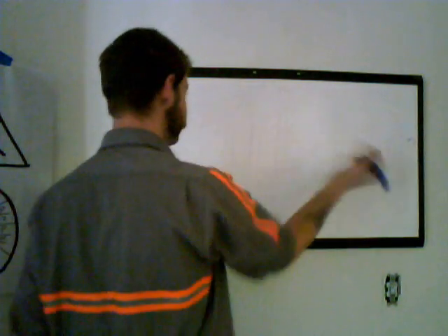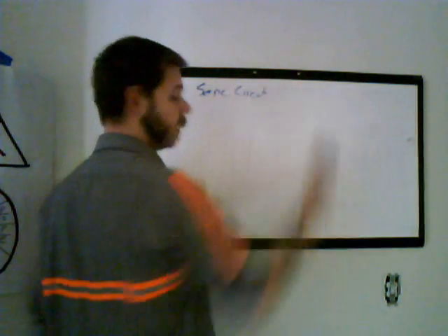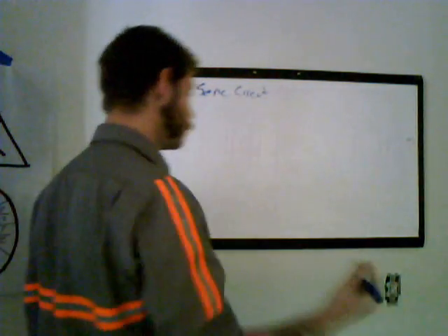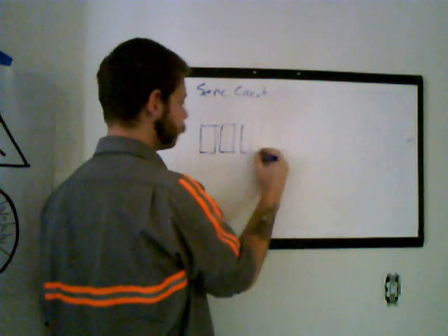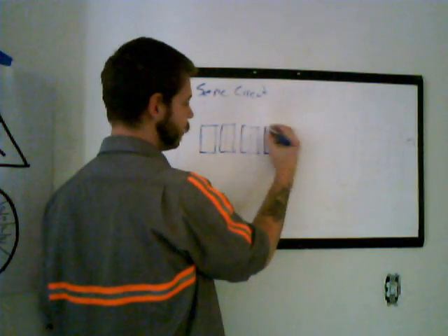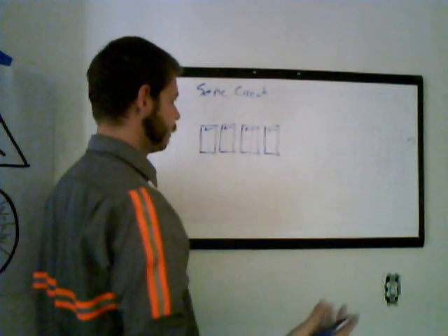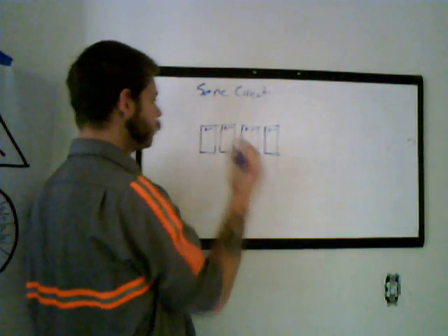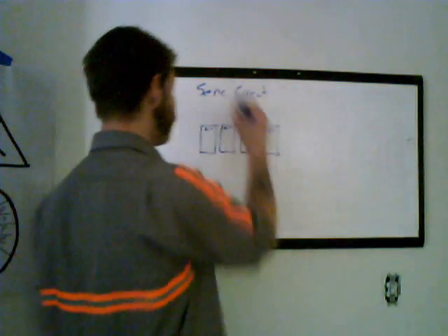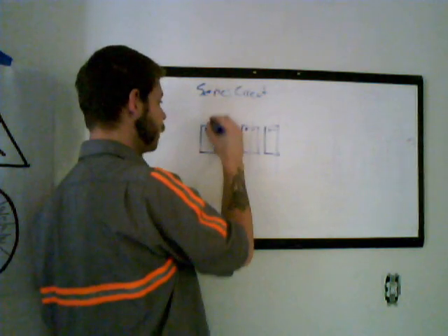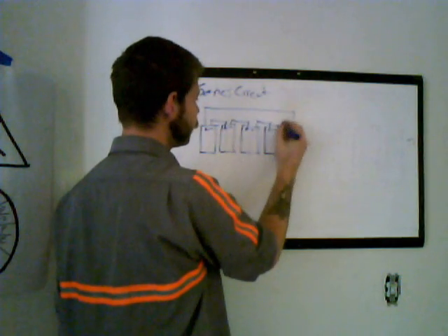Okay, so series. We just finished going over basically series loads. Let's put some PV panels together. PV panels are sometimes drawn like this, just because they're square and they get connected at one end. Just as connecting those light bulbs in series, all you have to do is connect the negative to the positive in all of these, and they'll be connected in series. Just like that.